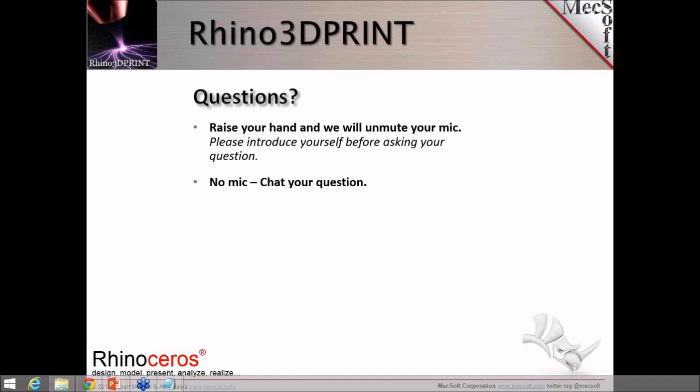But Joe, as far as manual support generation, I remember Uday showing an analysis where there are possible problems where support generation would need to be created. Is that in there? Yeah, there's an overhang detection algorithm in the product. When you detect overhangs, it'll color code the model. Uday, if you want to quickly bring up the product, we can show that. You can use the Rhino tools to actually create supports right now, but that's a manual process. So we are looking at automating that.